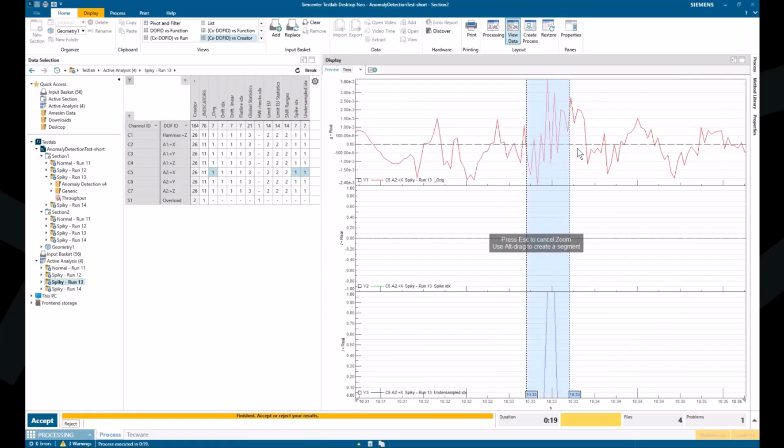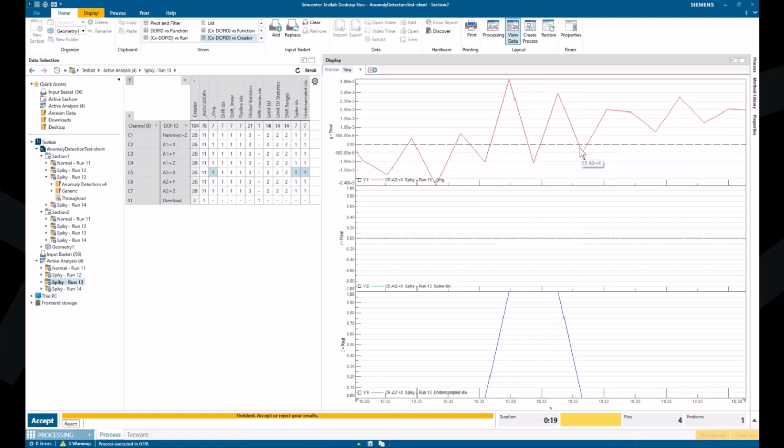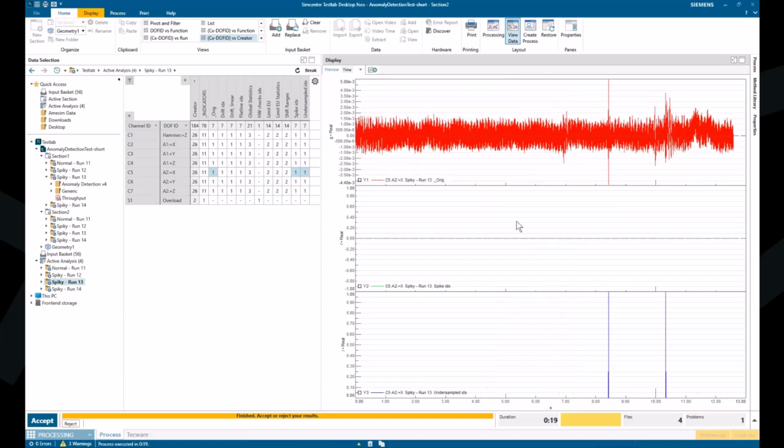The nice thing here is, since you get all this information in the result as to where you find this particular problem in the signal, it's very easy to go to these points and check whether this is correct or not. And again, if you check this, there are two options. Either you say, I have to change the parameters to make sure that this is not detected anymore because I think it's okay, or you make sure that this is corrected later on in the process by removing that segment or by applying the corrections that we have in the methods.